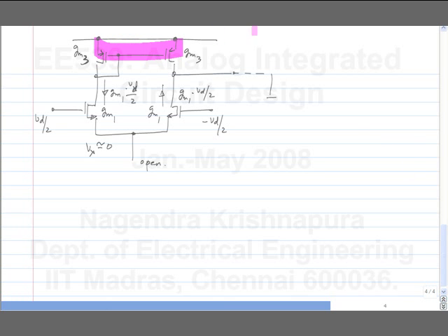Okay. Or if you want to calculate it further, what is the voltage at this point? It is minus GM1 by GM3 times VD by 2. It got a little cramped there, but it's minus GM1 by GM3 times VD by 2. Okay. So what is the current induced by GM3 here? This voltage appears across the gate source of M4, which is this transistor. And that gives you a current GM3 times this entire thing, which gives you GM1 times VD by 2. Okay.